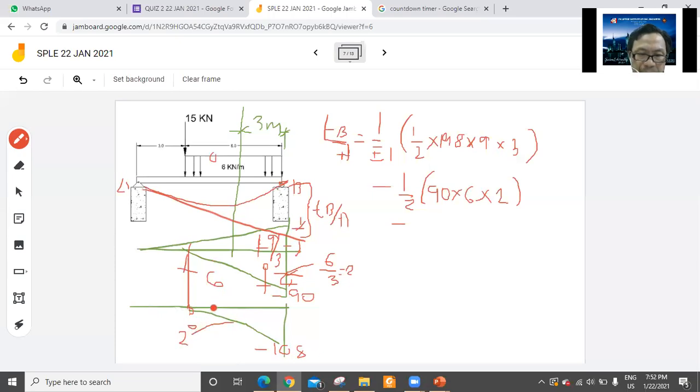Okay, very good. Minus. The area is 1 over n plus 1. That is why a triangle, which is first degree, has area 1/2, since n is 1, 1 plus 1. So this one is second degree, that becomes 1/3 of the height, which is 108. I will not put the negative anymore, since I'm already negative here. Times 6. The centroid is coming here.